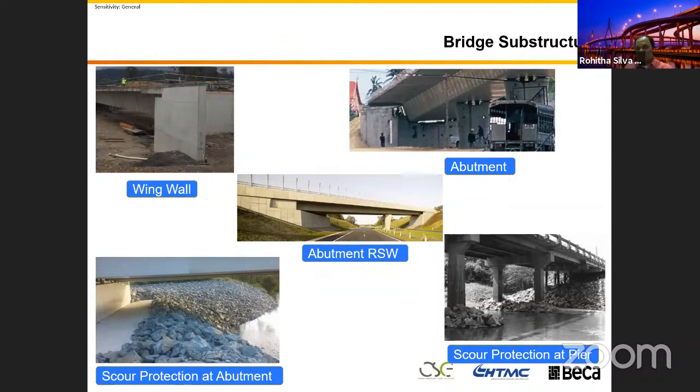If you build in an area with space, you can shorten this wing wall. Otherwise, you need a wing wall to hold the soil around here, because otherwise, with the loads and the deformation in the structures, this area of the bridge in the approach section won't last the intended design life. These are the different forms of wing wall and the abutment substructures. And this is one for the segmental box girder.